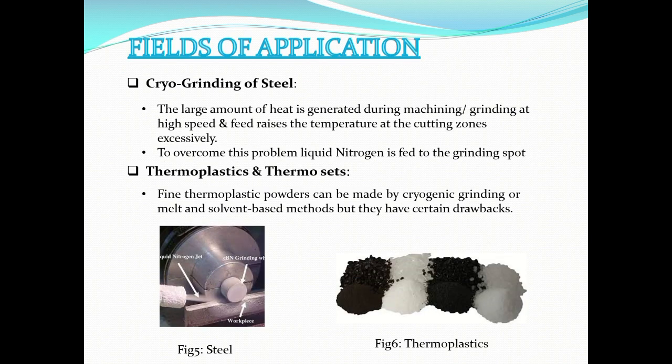Fields of application: cryogrinding of steel. A large amount of heat is generated during machining or grinding at high speed and feed, which raises the temperature at the cutting zones excessively. To overcome this problem, liquid nitrogen is fed to the grinding spot.